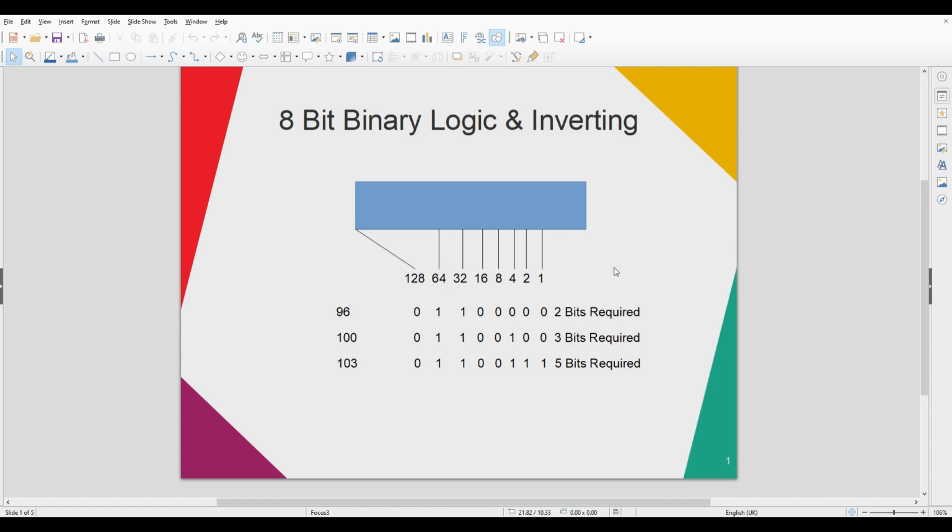We can use our 8-bit AND gate as our standard, and we need to invert all the other bits, so all the zeros we turn to 1s, because we just need to turn on our AND gate when we know our 1s are on, and the other zeros we'll just turn on for the heck of it. That's an easy way, but we need more chips to do that.